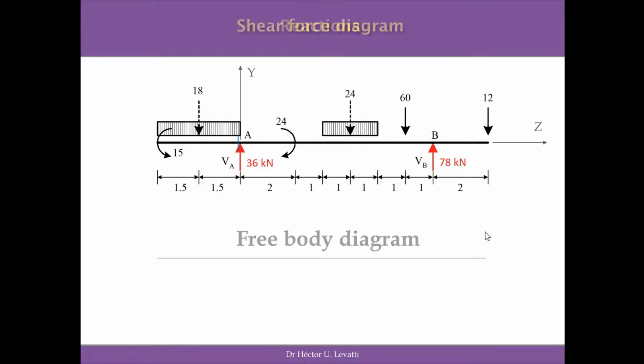In this occasion, I'm not going to use equations. I'm going to sketch directly the shear force diagram, looking at the structure directly and explaining how to do it when you already understand exactly what this concept is. So we are going to sketch the shear force diagram. We are going to consider that A is our origin of coordinates. So Z is the horizontal axis, as you see here, and Y is the vertical axis. So this is the origin of the coordinate system we have established.